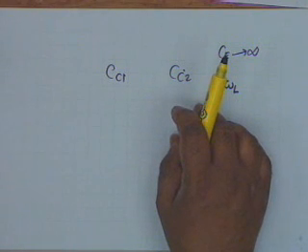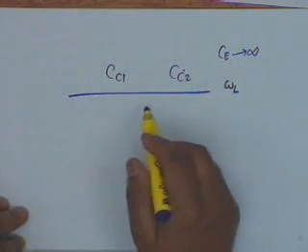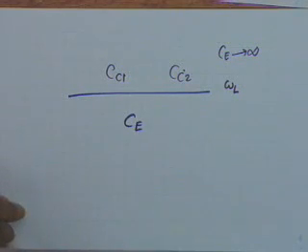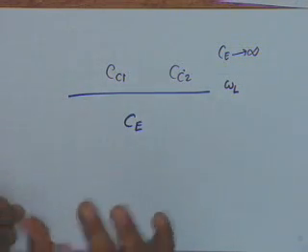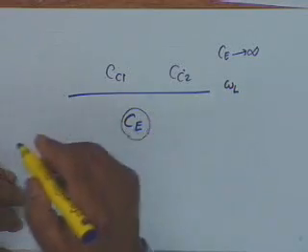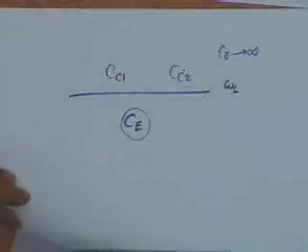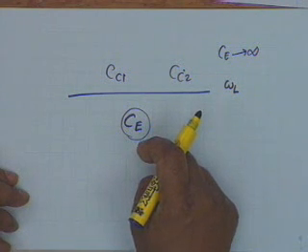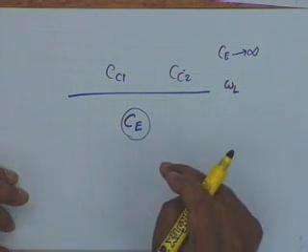That's a different situation. In our situation, we are determining omega L by CE and trying to find out what should be our values of CC1 and CC2. Whatever you calculate CC1 and CC2 from the given omega L, you multiply 5 times. Then it will make sure that omega L determined by CE is the largest of the 3. And so this will determine the low frequency 3 dB cutoff point.